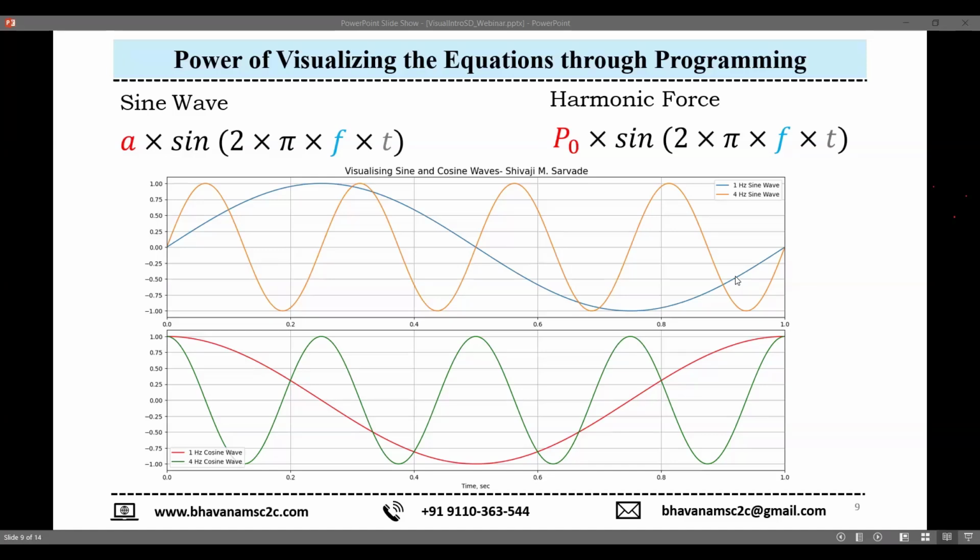That is one more particular phenomenon that you must all be familiar with, because we use this day to day in our structural design practice. We always have to avoid resonance. If you are doing machine foundations, it's extremely crucial. Unless you know frequencies and analysis for frequencies, you cannot design a foundation, or a slab for that matter, or any structural element for that matter. All this is possible if I have some power of visualizing the equation.